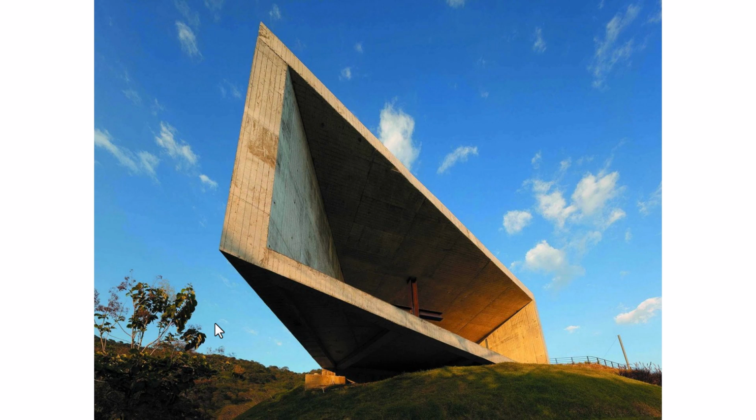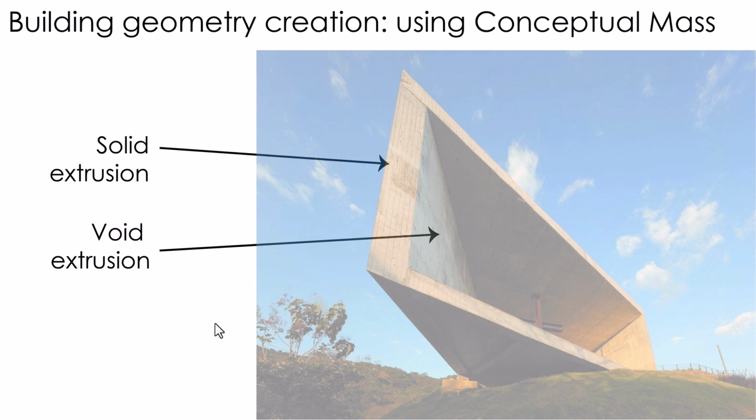Now, other objects, they look really dramatic, but in fact, these are really simple. It's basically just a rectilinear extrusion, this kind of pointy shape that is extruded straight up. And then there is a void, or you could use a void to eat away at the interior. And any other elements that show up here, these look like I-beams, W-sections, they call them.